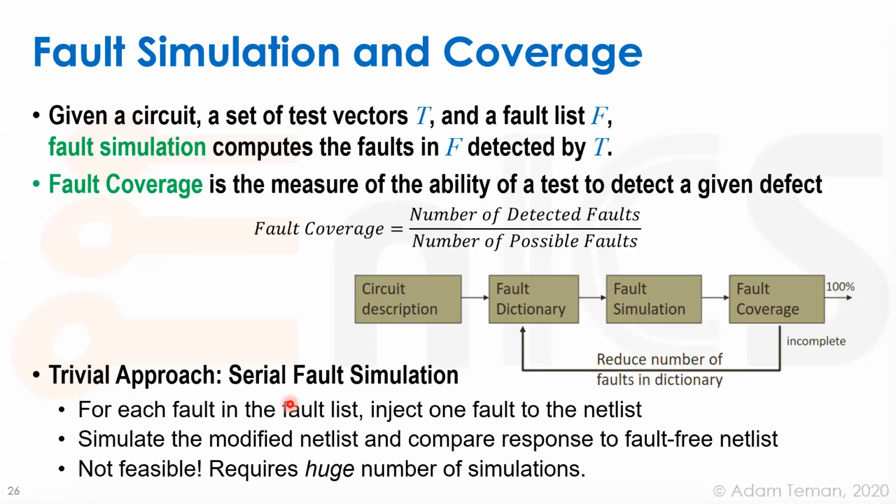So the way to test whether your functional test is covering or not, there is no other way to do it other than some kind of fault injection, and they're doing it on emulation systems like FPGAs and so on. And I believe that even today, the high performance CPUs don't want to spend stages or make their paths longer just because of scan muxes and so on. So they base much of the tester patterns on functional and self-tests. And then they need to prove that it provides good coverage.